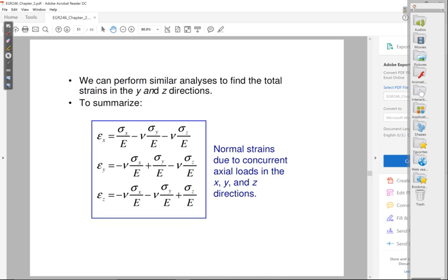And if you remember, I said something like rubber that's incompressible, okay, basically it's the very limit of what can happen with the material when you apply multi-axial loading. In an incompressible material, your volume never changes. It doesn't matter how much you strain your part. Okay, you take this cube, you apply stresses in all three directions. The volume never changes. It could deform, it could change shape. Okay, it could go from square to some kind of a rectangular box, but its volume never changes.